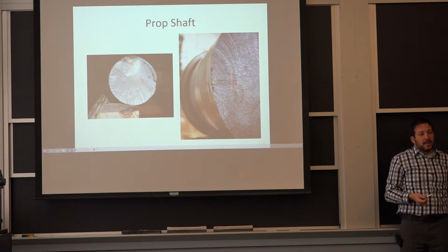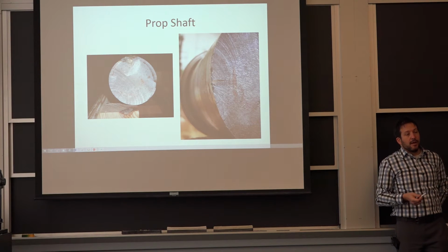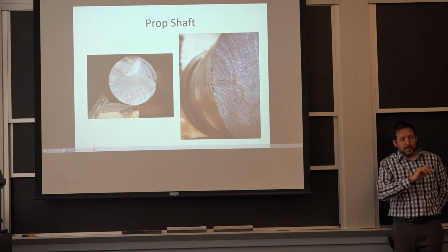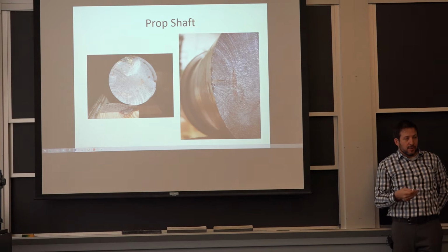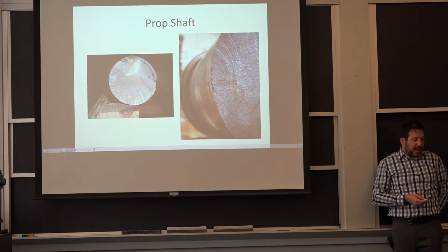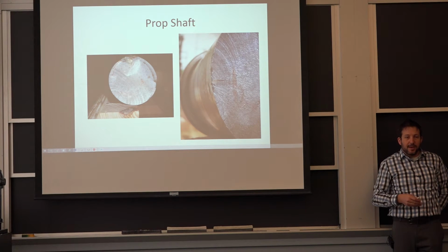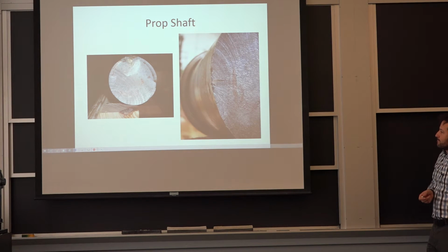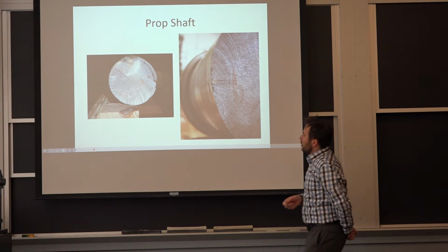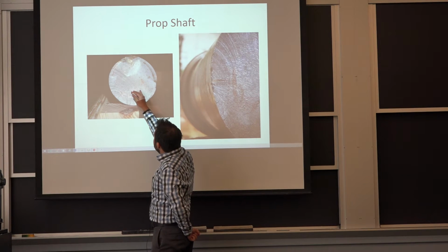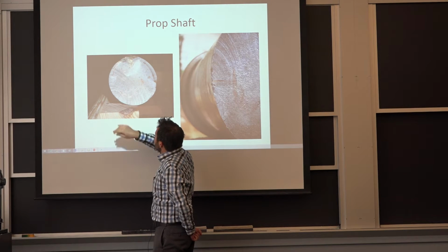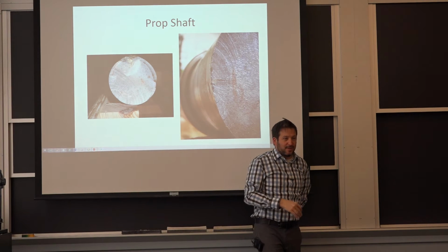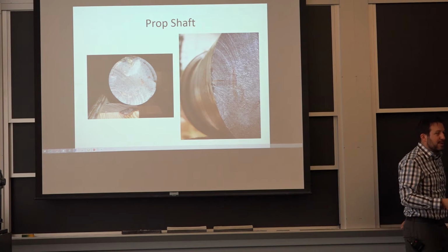So when you have something that fails over time, plastics especially are very notorious. If you have just even a scratch on the surface, if the loads are significant, that's where the crack is going to start. So the crack starts, and it goes through a certain growth rate, and there are equations to predict that almost exactly, and then it fails. Now, once it's failed, what can you do? Well, you know that you did have a certain load, but the load was nowhere near the yield strength, because you cracked 40% through your section.